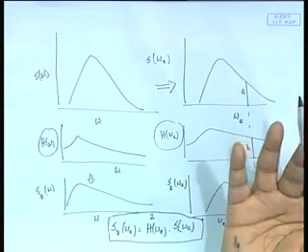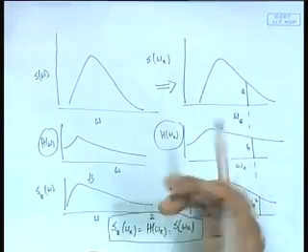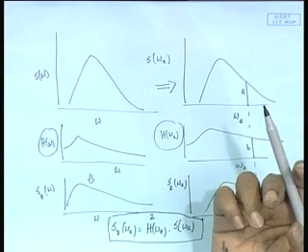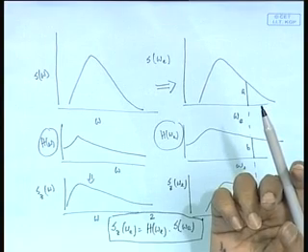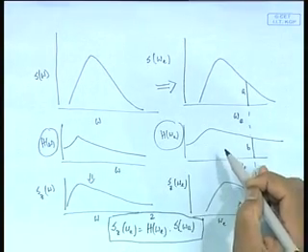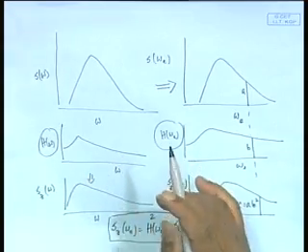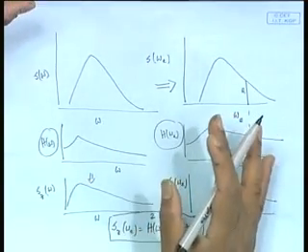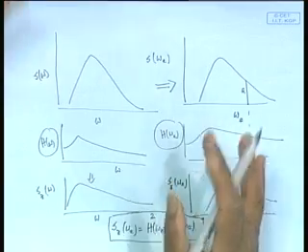RAO is just a term. So, when I say find RAO, I am telling you to find out how the body behaves in regular waves. This graph, RAO or transfer function, is a representation of the response in regular waves.